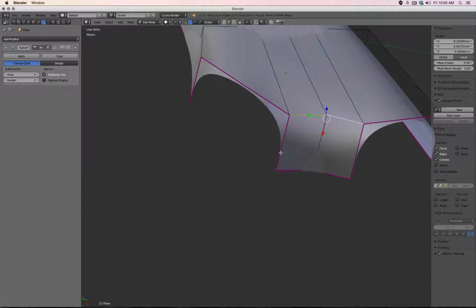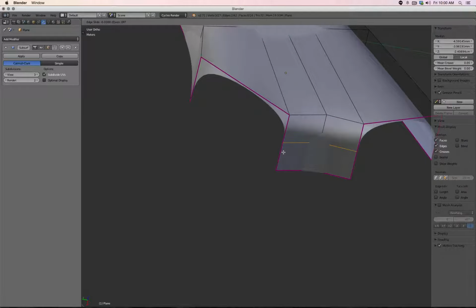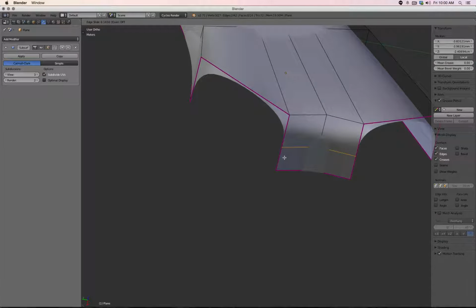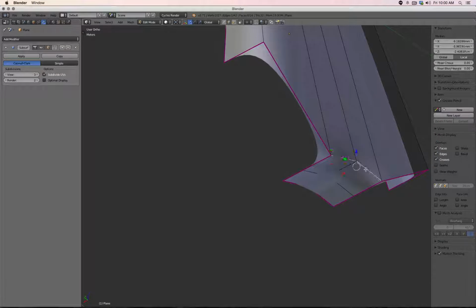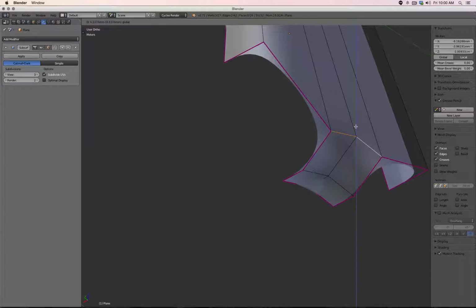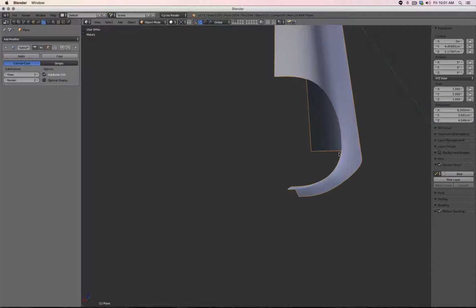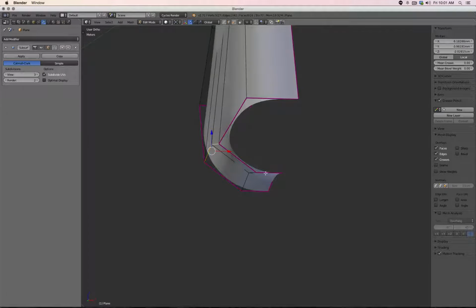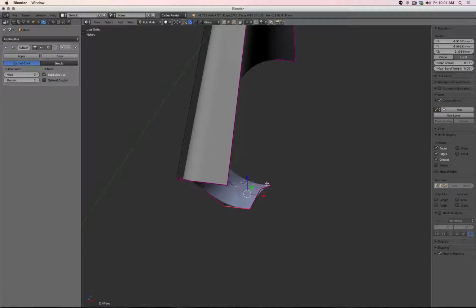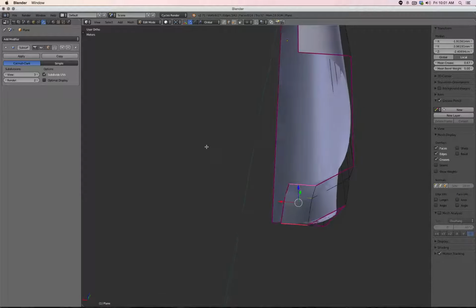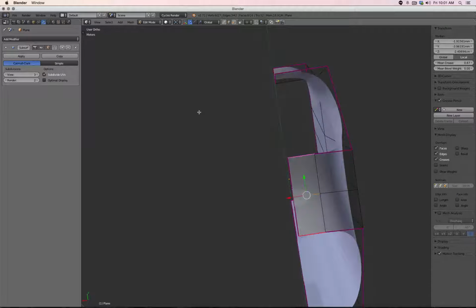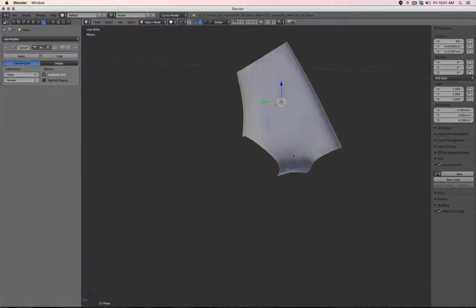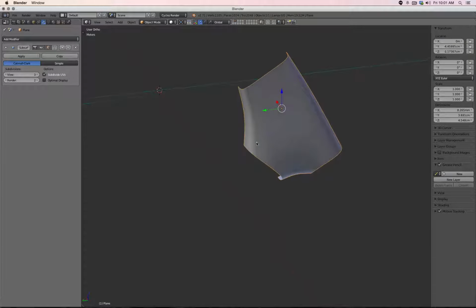So maybe there actually in this case I'm going to add a loop cut, maybe there, and then push this one in. So this way you see I stabilize this lower part. See the same thing again, what I do in Alias, I also work this way with polygons and sub-D modeling, because essentially this later will be a NURB surface out of 1, 2, 3, 4 faces.